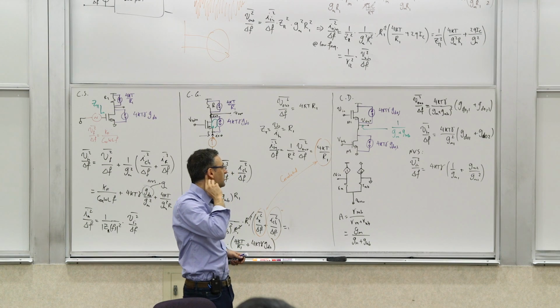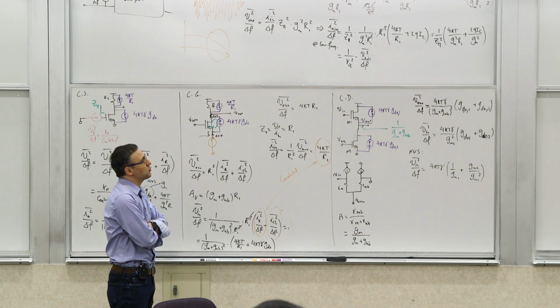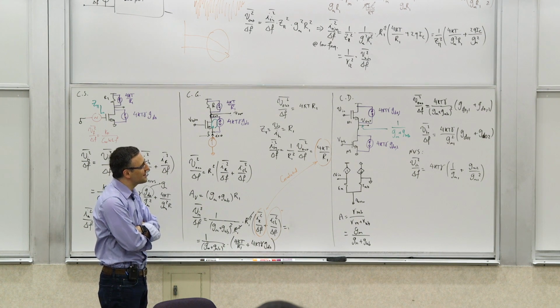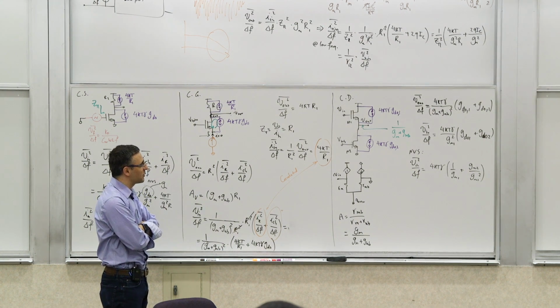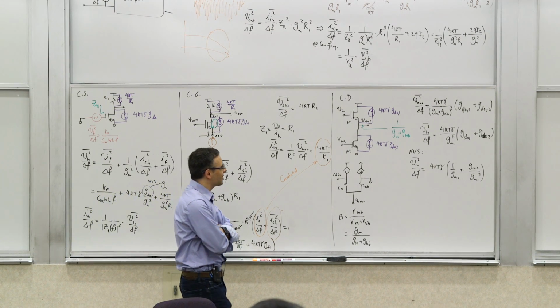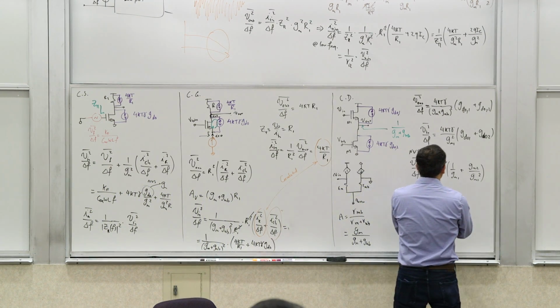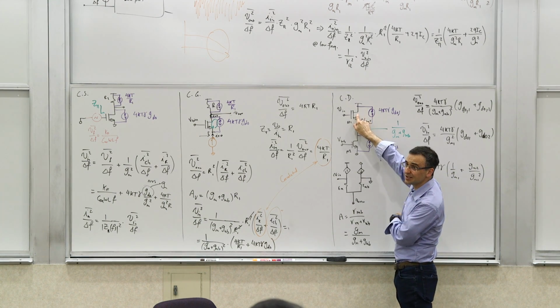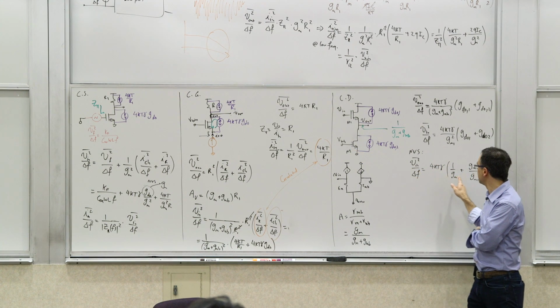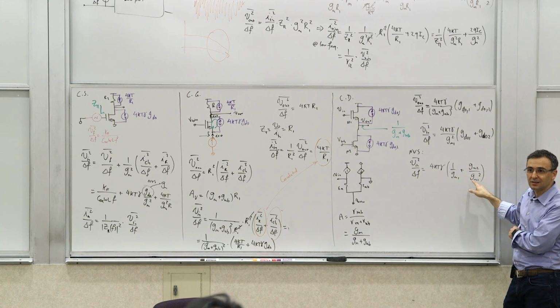So what does that tell you? That tells you that if you want to reduce the input referred noise of this thing, if it really matters to you, generally they're not as important in this case because they don't have that much gain, but still you need to worry about it. You don't usually put these at the first stage, and that's what matters the most. But yes, you need to get a higher transconductance here, but the transconductance of this guy actually is damaging, right?